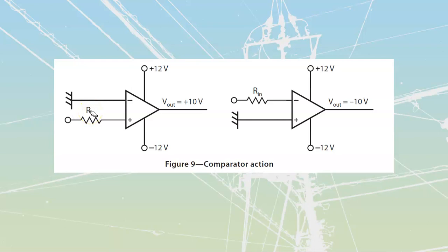We'll go back to this one over here. They've got comparators in action. They're going to say, what would happen if we get a value of voltage in? If I've got 1 volt, will that 1 volt be higher than ground? Absolutely, it will be higher than ground, which means that 1 volt multiplied by, because this is open loop over here, 200,000 means that it wants to stick out 200,000.